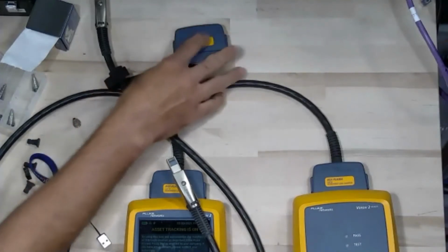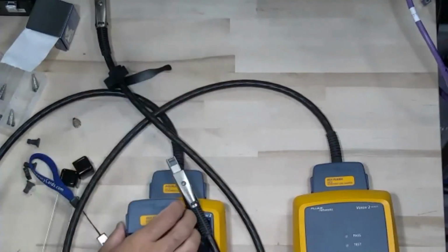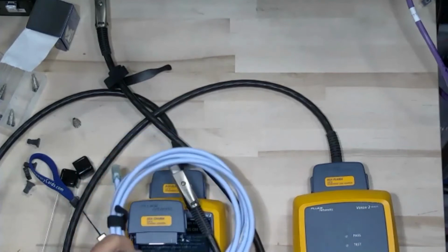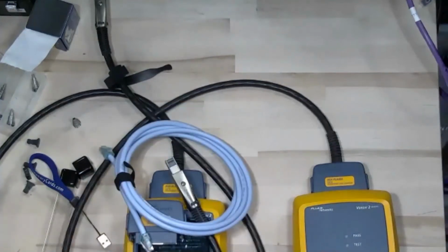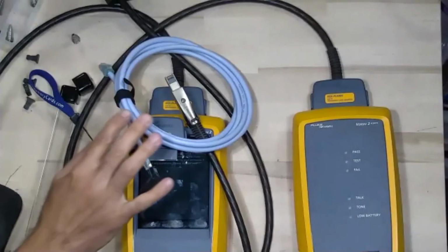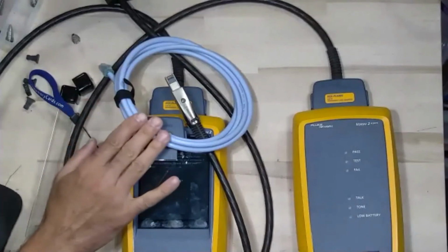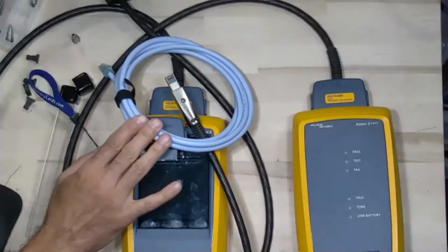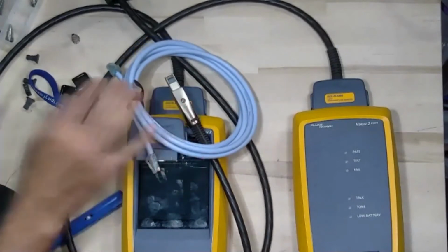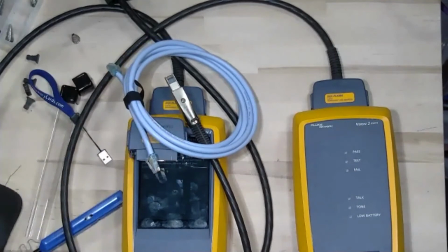Occasionally, we will see channel adapters show up. Now the channel adapter right there is designed to be used with a patch cord. But here's the thing. That test is only valid if that patch cord is left in place. So if you have the patch cords and those patch cords are going to stay there, it is okay to do a channel test. But if we're taking this patch cord and moving it from one connection to the next, that is an invalid test and it is wrong.